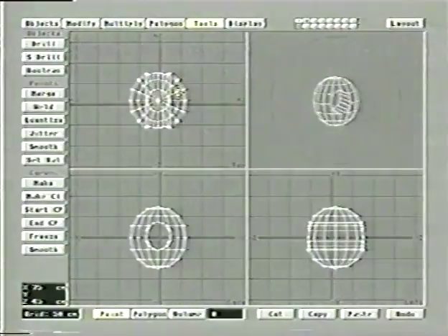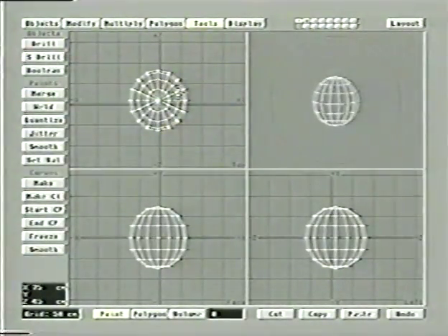Let me just undo that for a second to go back to our regular sphere and show you one other quick use for subtract so you see the idea. In this case, we pulled the disk straight through the sphere. Let's do another one where we don't actually completely remove it, where we just take a chunk out of it. And the example I use here is a jog shuttle wheel on a VTR. The wheel itself is pretty straightforward. That's a disc. The trick is getting that thumb notch. And with booleans, it's no trick at all.